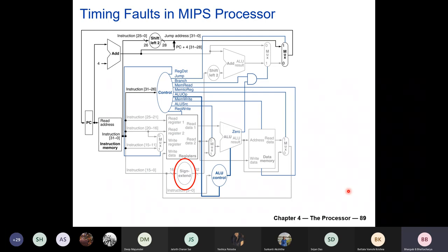So those are logic faults. There is another kind of defect we call the timing fault. That means no line is stuck at 0 or 1. I mean, they are fine. They can assume logic 0 and 1 as in the fault-free case, but they are supposed to perform the operation within a certain delay. But the module has become slower. Somehow it becomes slow. It is giving you the correct result, but not within the specified delay. The delay of the logic might have increased.